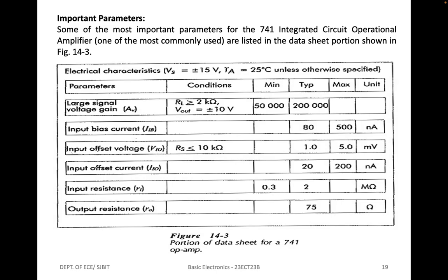Common mode inputs are voltage changes that are applied simultaneously to both input terminals of an operational amplifier. The common mode input voltages can be passed to the output. Common mode rejection ratio, expressed in decibels, defines how good the amplifier is at attenuating common mode input voltages.